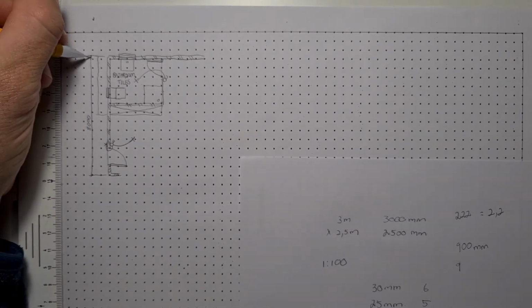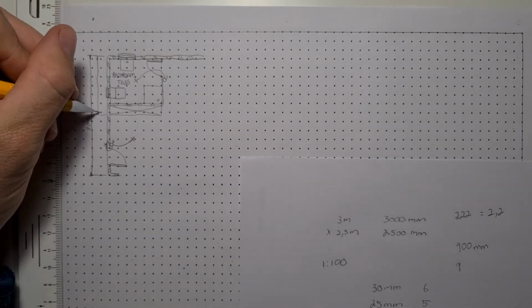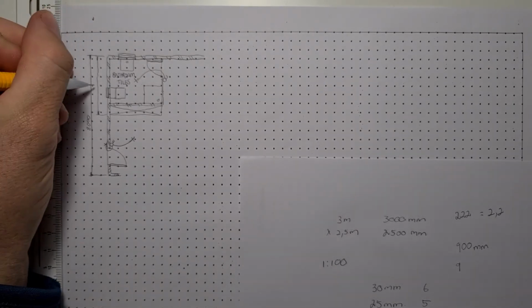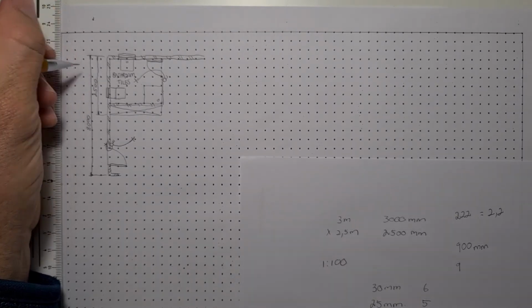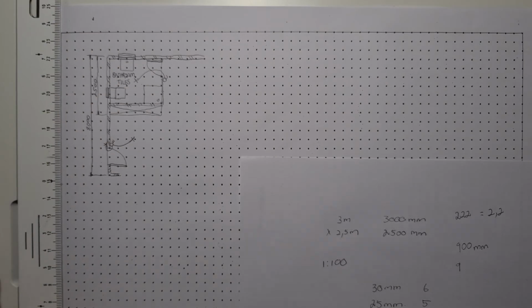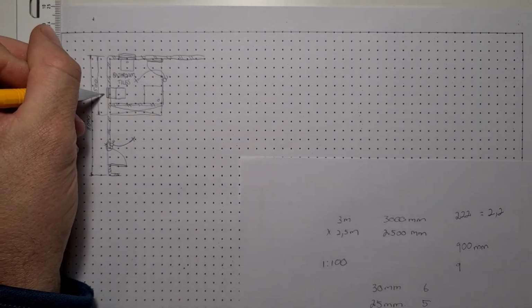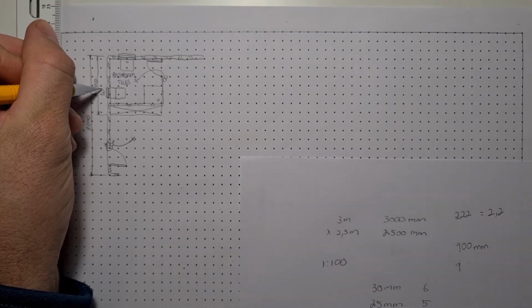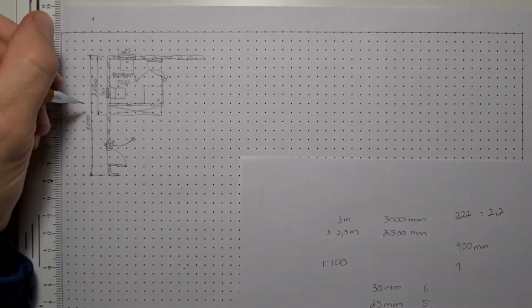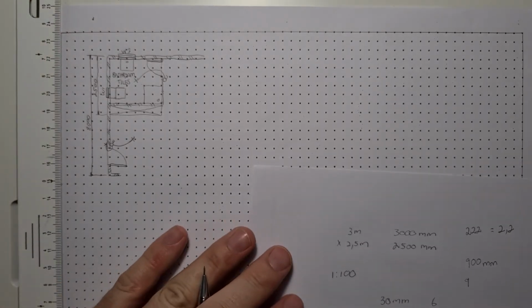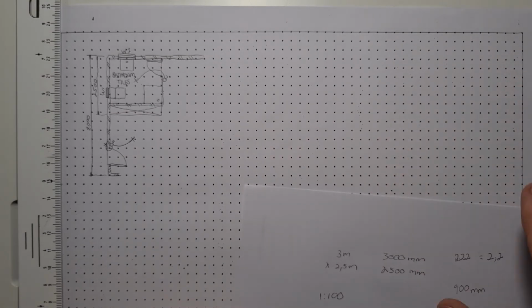Now I want to add in the dimension for the bathroom. So I'm just going to make that darker there and that darker there. Make the corners darker there. And this is 2,500 millimeters. I don't need to write millimeters. For the windows, I can either just label it as window 1 and this one window 2 because they are different sizes. And then in some sort of note section over here, I can add my